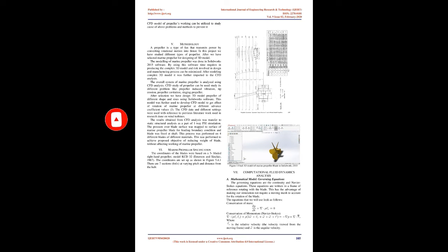4. Problem definition. A propeller is the most common propulsor on ships, imparting momentum to a fluid which causes a force to act on the ship. The ideal efficiency of any size propeller, free tip, is that of an actuator disc in an ideal fluid. An actual marine propeller is made up of sections of helicoidal surfaces which act together screwing through the water, hence the common reference to marine propellers as screws. 3, 4, or 5 blades are most common in marine propellers, although designs which are intended to operate at reduced noise will have more blades.